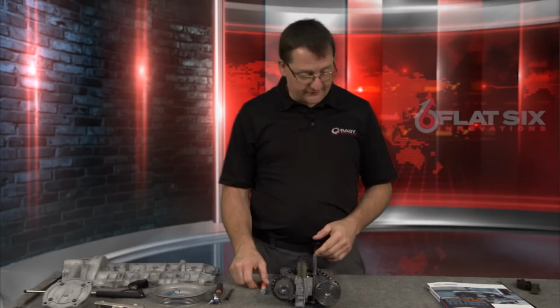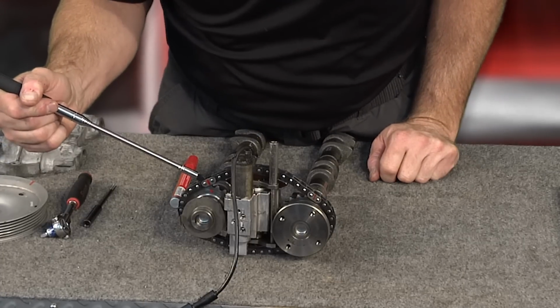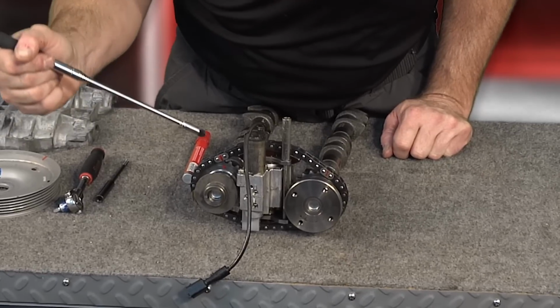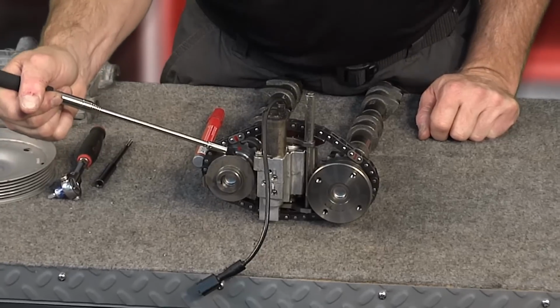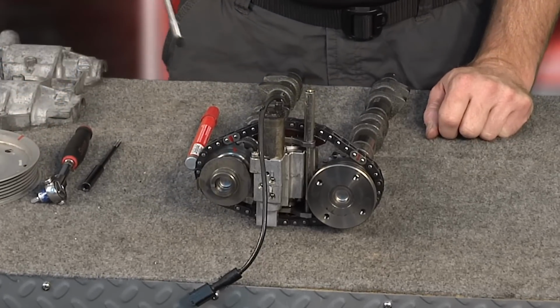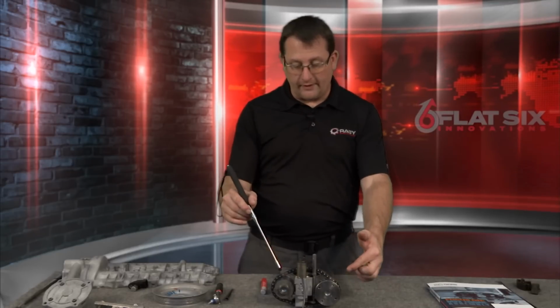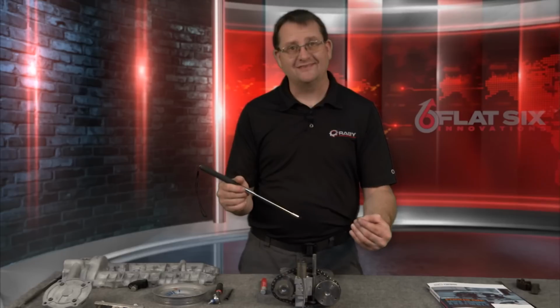Okay, so if your engine is original and has not been apart, you're going to see that it has two discolored links on the timing chain, on the simplex chain. One is here and one is here. I've marked these in red. There's also a small dot on each camshaft that I've also indicated in red that you can see here. This is the only allocation that you really need to mark. The dots are indented in the camshaft, kind of an embossment that you can see, but I mark them red so it's easier for me to notate them later on and easier for you to see them here.